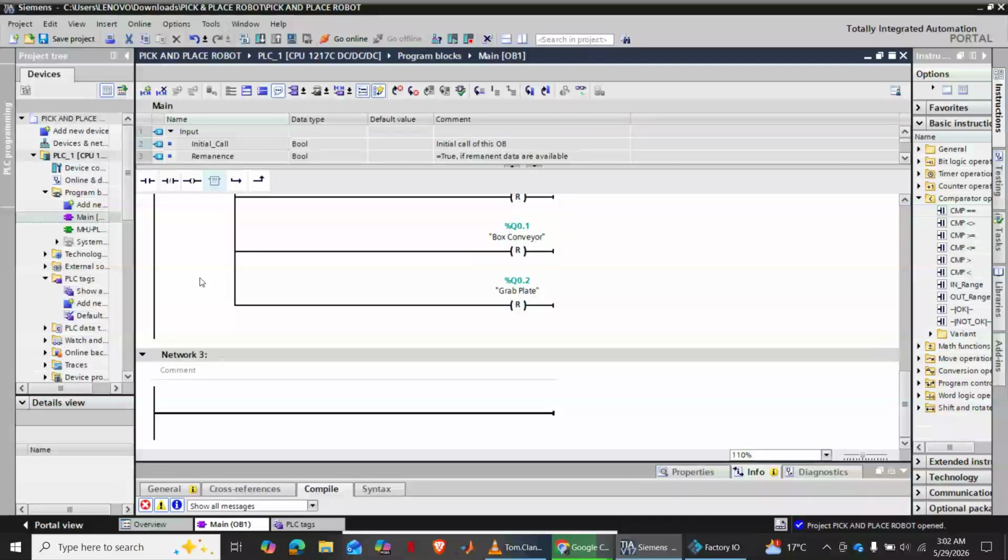How do we stop the conveyors? Stopping the conveyor. Here we are talking about stopping the conveyor when stopping the conveyors, not resetting, stopping. So you remember I said that when we detect a stackable box the conveyor must stop, and when we detect a plate too, which is the raw material, the conveyor should also stop. So you saw there I had a plate sensor for stopping the plate conveyor, and I have a box sensor for stopping the box conveyor.